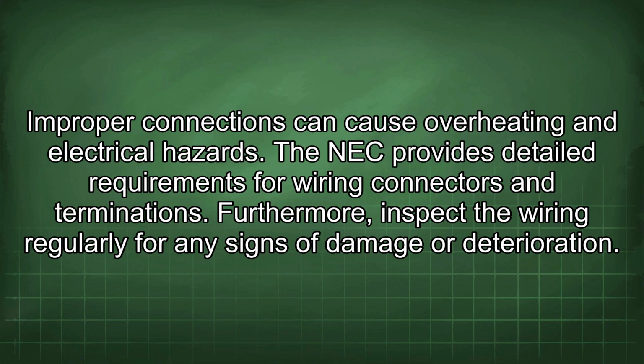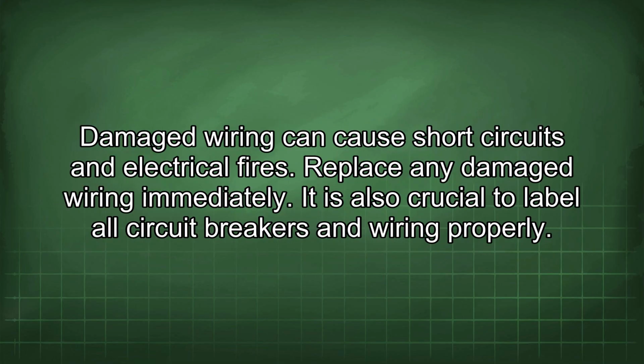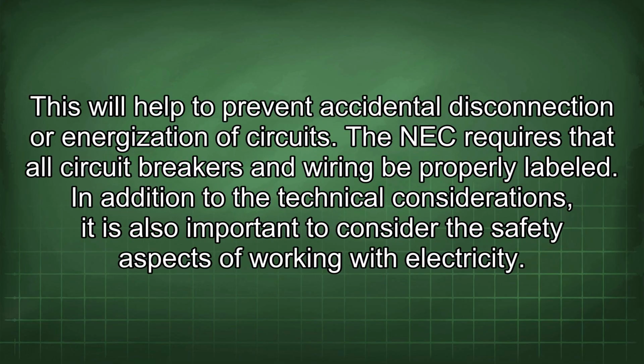Furthermore, inspect the wiring regularly for any signs of damage or deterioration. Damaged wiring can cause short circuits and electrical fires. Replace any damaged wiring immediately. It is also crucial to label all circuit breakers and wiring properly. This will help to prevent accidental disconnection or energization of circuits. The NEC requires that all circuit breakers and wiring be properly labeled.